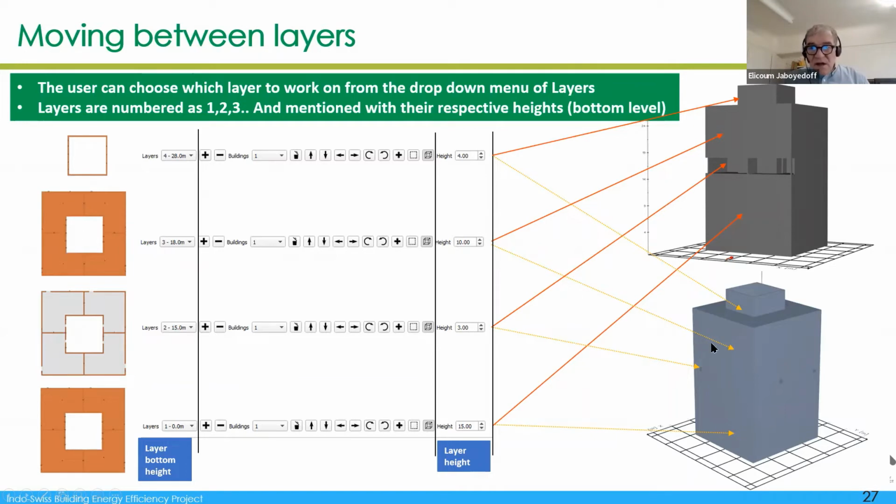Then we have the higher portion of the building, which is again in a block form, but which still has the courtyard open like the bottom. And then on top of it, at the height of 28 meter, which is here, we added a kind of chimney above the building, which helps in creating a negative pressure in the courtyard with the wind passing above the building. So you can see that this is one way of adding layers and using layers to make